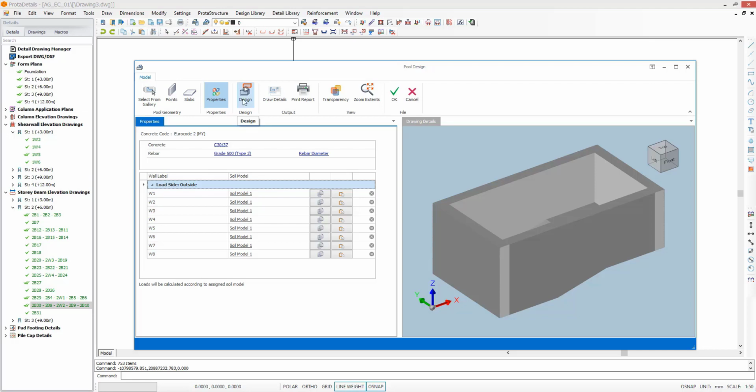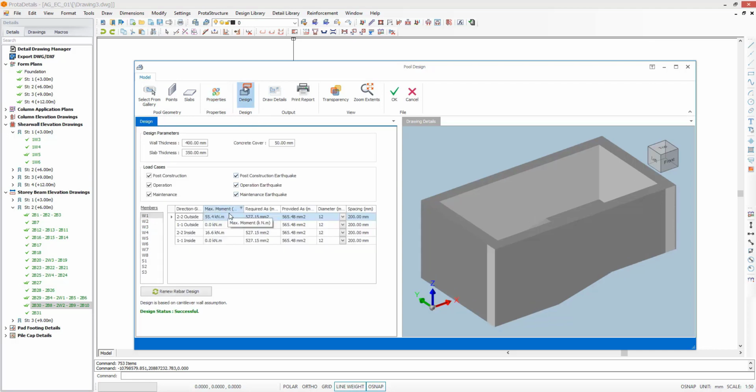And finally, what I do is I just click the design button. And design is done, and of course you can play with the resulting design, and you can actually change the load case scenarios, etc. The stability checks and RC design, reinforced concrete design, under service and design scenarios are done automatically here.